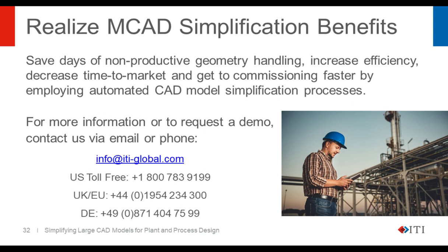No, I'd say we start off with the original CAD model inside CADfix. We simplify it. They are different. They are changed parts or changed models. We can undo and go back. We have some links deep down inside CADfix where we know that this simplified part came from an original complex part, but it's not something you can quickly switch between in a live session. You've either got the original model or the simplified model.